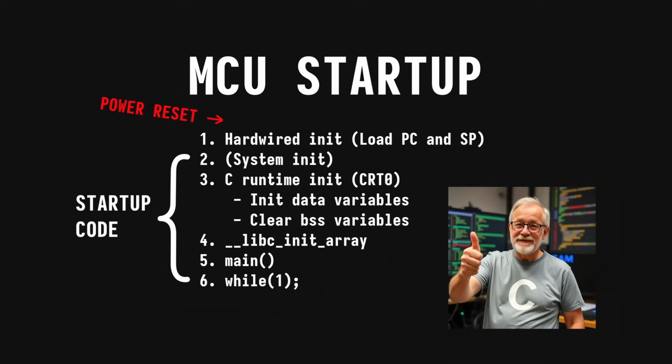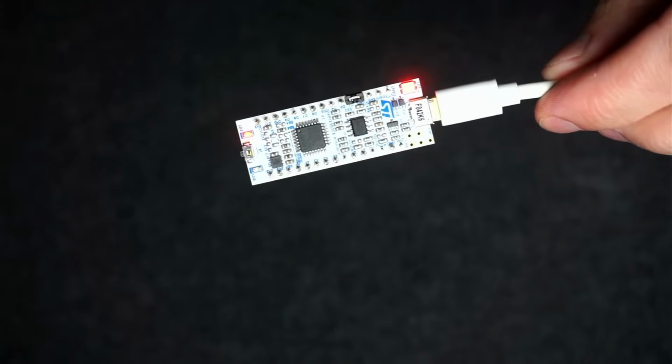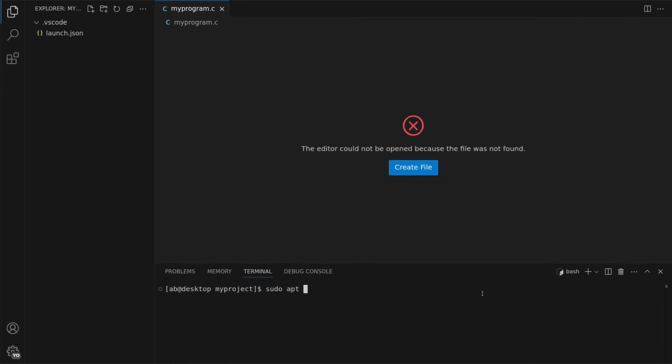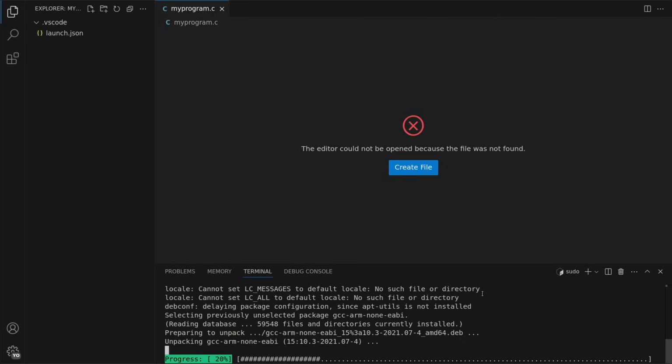Now that we are more familiar with this process, we are going to discard the startup code we just looked at and write our own from scratch. We will target the same microcontroller, but we will not build the code with CubeIDE, but instead download the ARM GNU toolchain. CubeIDE wraps ST's own build of this toolchain, so this shouldn't be too different, but it allows us to play with the toolchain more directly.